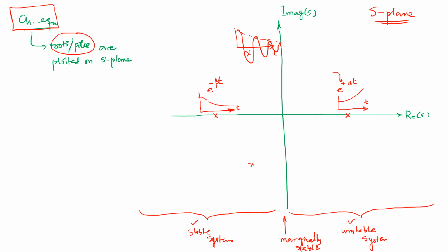And that is what we have reached to this particular stage after we have got the characteristic equations, after we have understood or found out the transfer function. And that is why the Mason's gain formula is going to help us out to transform the graphical representation of a system into an analytical expression, which we can further manipulate and observe to comment on different aspects of the system. So that's why this is important.